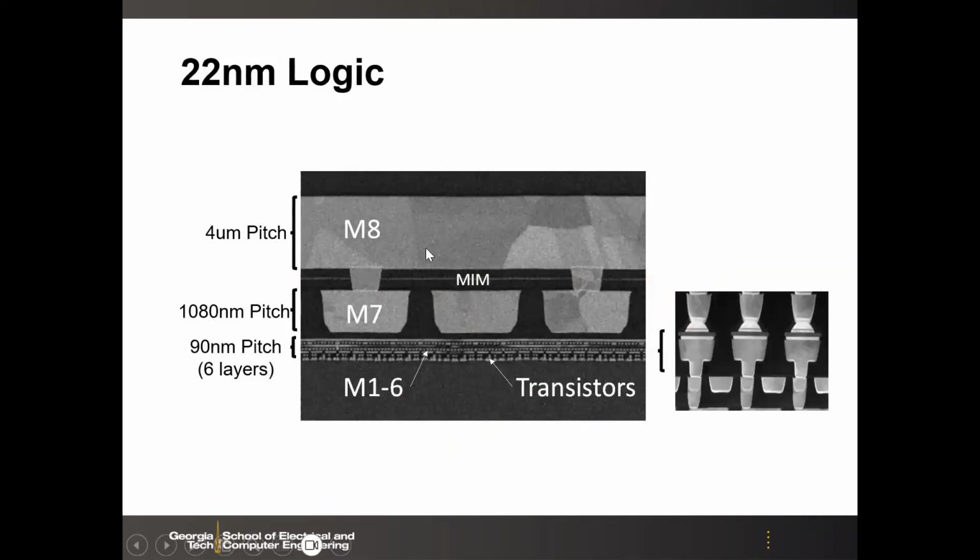So here is a larger view of this cross section. RRAM is very little here, between metal 4 and metal 5. And the underlying is a transistor, very small, and then above that is high level metal, global metal for your power supply and so on. So it's very large on the metal 8 in this case.